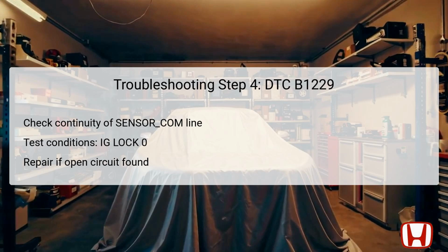However, if continuity fails, this indicates an open in the wire between the climate control unit and the sunlight sensor, necessitating a repair of that open circuit. Without addressing this, the climate control system will remain non-functional, resulting in an incomplete diagnosis.